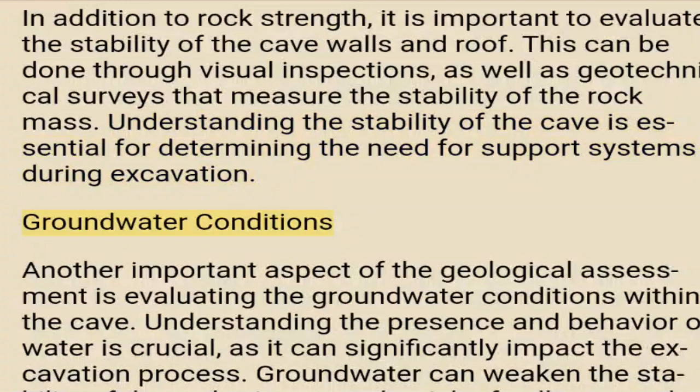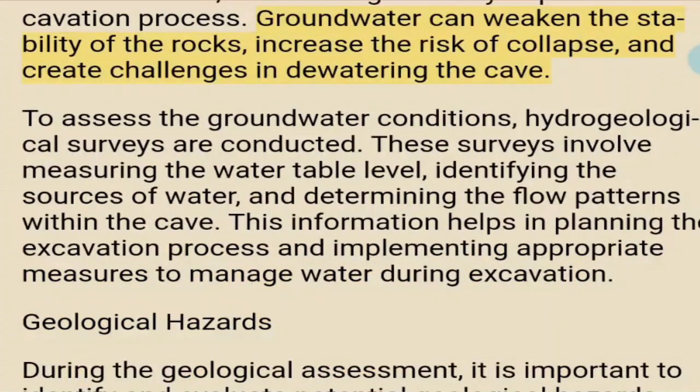Groundwater conditions. Another important aspect of the geological assessment is evaluating the groundwater conditions within the cave. Understanding the presence and behavior of water is crucial, as it can significantly impact the excavation process. Groundwater can weaken the stability of the rocks, increase the risk of collapse, and create challenges in dewatering the cave.